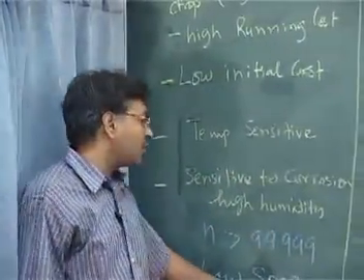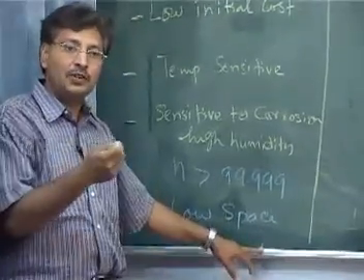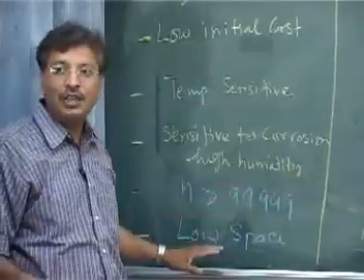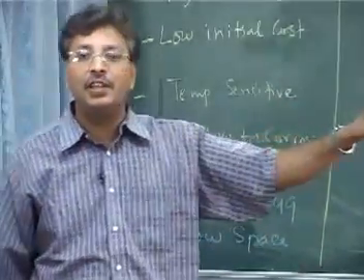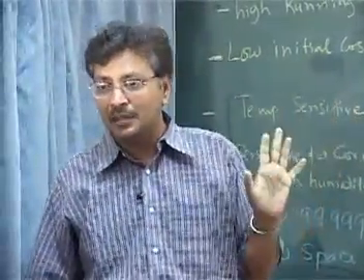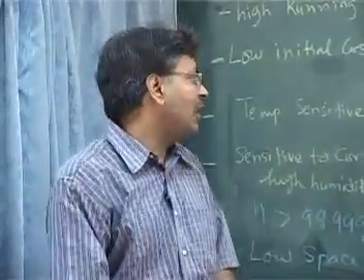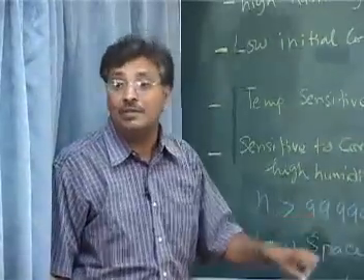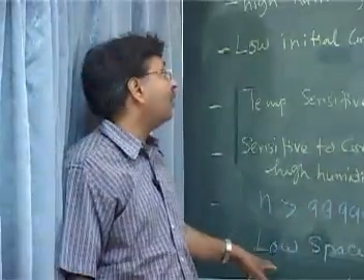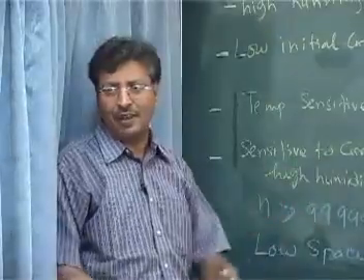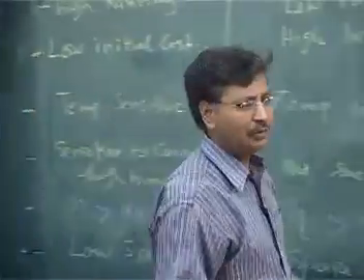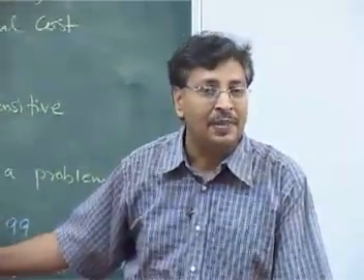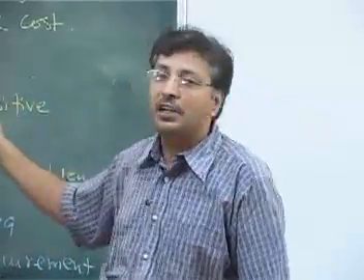If the gases are combustible or an explosion is possible because of the nature of the gases, you will not go for ESP. You will always go for the bag filter, because there is no possibility of any chemical reaction happening inside the bag filter. For processes where the CO level or hydrocarbon level is very high, they will not go for ESP because of the fear of fire. But there is nothing to fear if you are dealing with inert dust like ash. So all the power plants in India have ESPs.